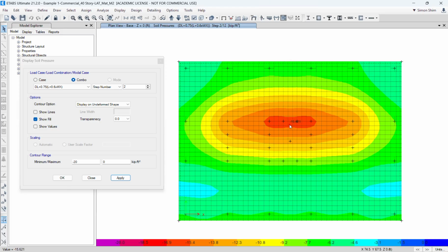So the center of the highest soil bearing shifted to the top right, on the north, which means wind is blowing from bottom to top. So I think you could include this procedure as a soil bearing check for our mat performance, and just confirm it should be less than our soil bearing capacity, right?